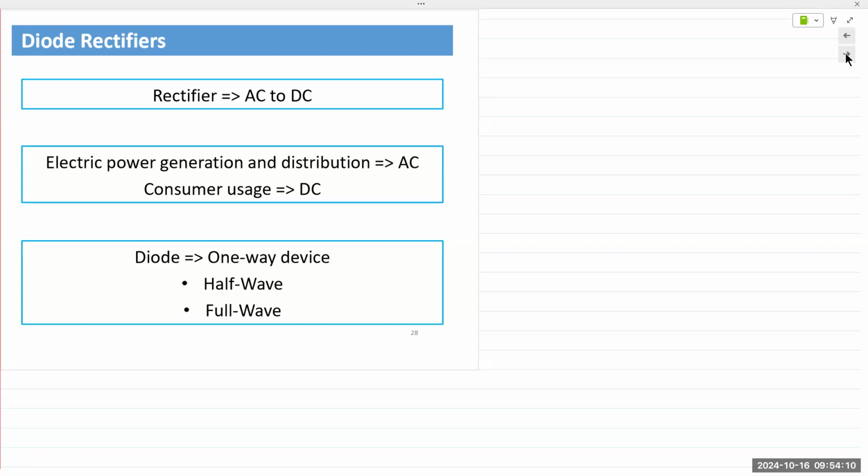So going back, going on a little bit of a tangent. AC power generation and transmission. Generation is very easy in AC because you have a rotating coil inside a magnetic field. So it's moving between a north pole and a south pole. So by its very generative nature, it is alternating. Okay, so it's very easy to generate an AC voltage compared to a DC.